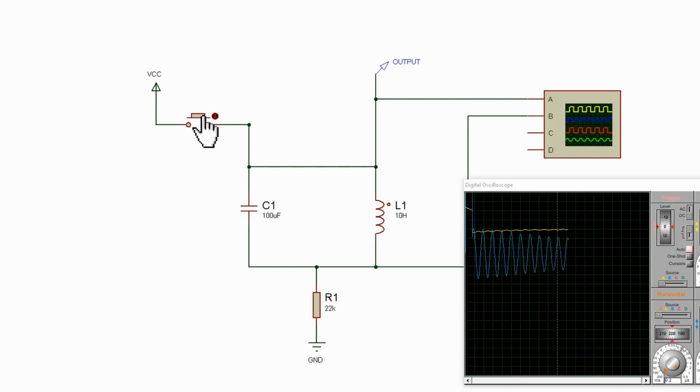Unfortunately, it's not a perfect world, and the energy actually diminishes just through the resistance of the wire and is transferred into heat. By adding a bit more energy we can create the oscillation again. So by creating an additional circuit that actually feeds some voltage back into this circuit, we could continue this oscillation indefinitely. Well, that's just a quick example of a very basic oscillating circuit, and that'll be all for today's video. And actually what we'll do in another video is cover the more complex oscillators.